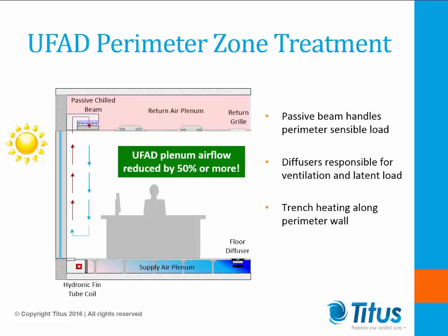System designs utilizing condenser water reheat, runaround coil face and bypass, and other strategies can be employed to solve this potential design problem. Other options include the use of a separate system to dry out air or the use of desiccant dehumidification. Another way to help solve the problem of thermal decay is by the use of sensible cooling at the perimeter. Sensible cooling at the perimeter is a great complement to the perimeter cooling of an underfloor system.